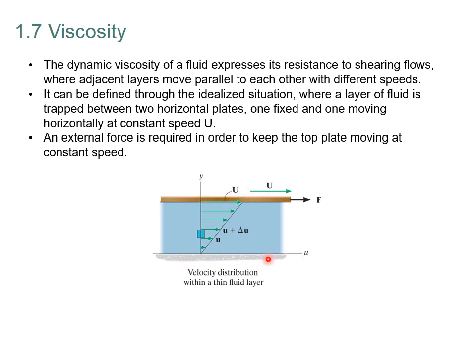The bottom plate is stationary. And so here you can see that shearing effect is going to cause the fluid to move at different levels as you go from the bottom to the top of the plate. So the velocity is not the same here. At this part of the fluid, the velocity is going to be higher, moving to the right, than it is closer to the bottom plate.